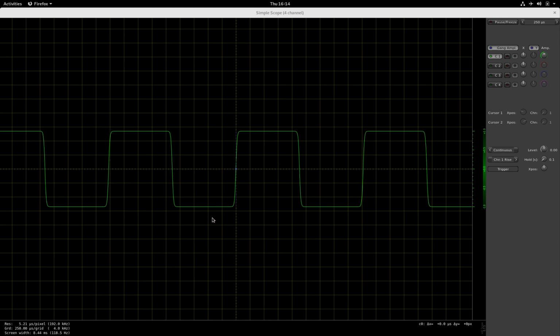But what I want you to notice is that even when the frequency of the signal is increased, the basic shape of the signal remains the same. So we will always have this soft clipped waveform and these rounded edges, and then the signal that flattens off like this. So I will now increase the frequency from the signal generator.